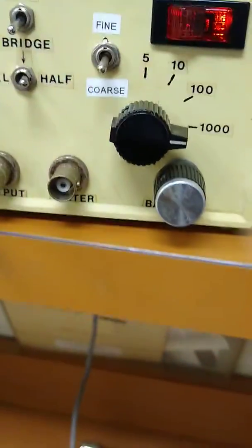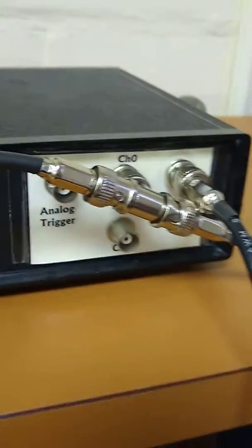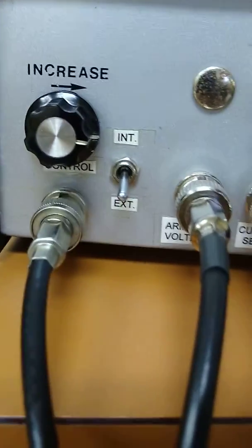Now, note that the cable that was originally plugged into filter on here needs to be connected to the channel 0 D to A converter. This is just so that the command voltage will be appropriately recorded. Make sure you set this box to EXT instead of INT, because we're using external control, not the internal control. And it is on with the power supply providing power to it. So when you click run,